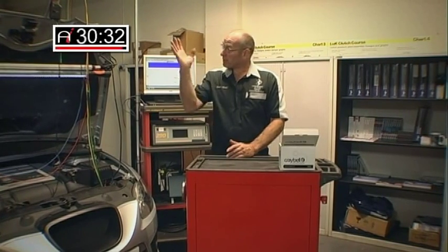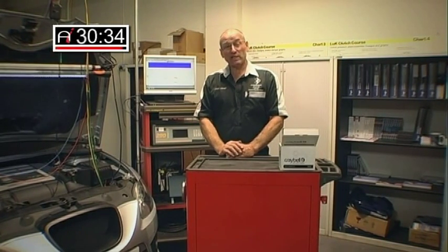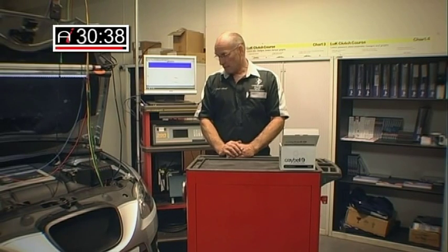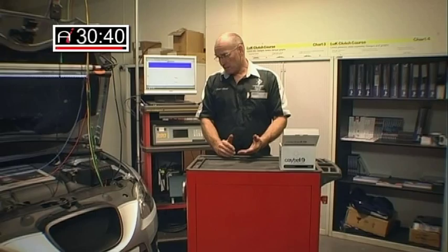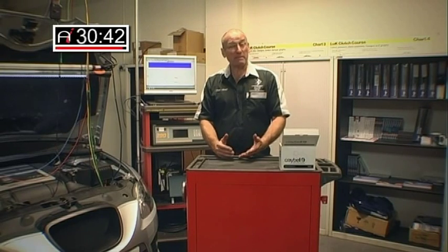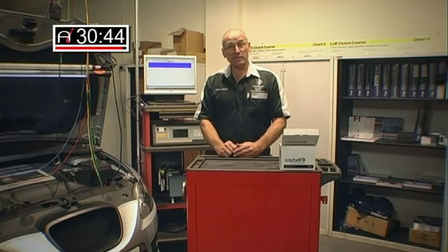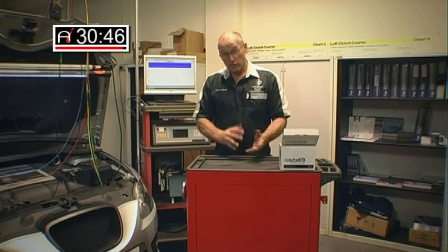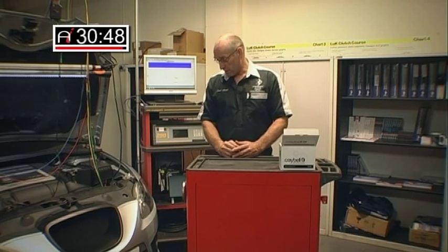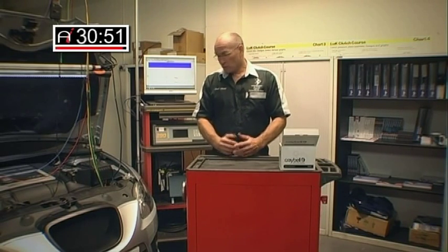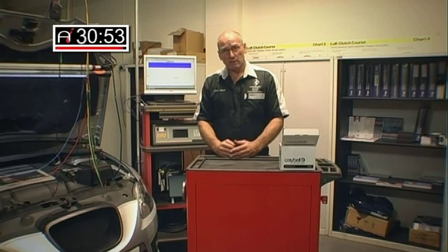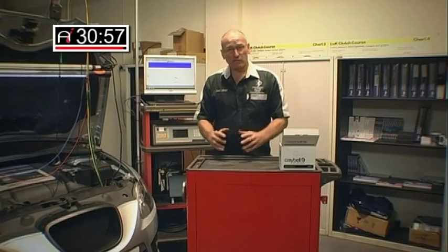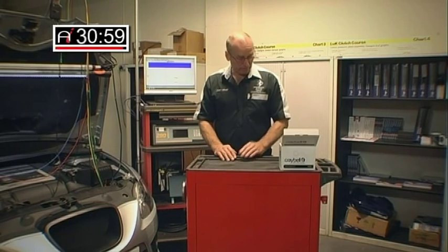The current clamp also serves very usefully for other very high speed current devices, such as anything that's now motor driven with PWM signal, where duty and frequency, and therefore current, change very, very quickly. Turbo control, motorized throttle body, EGR control, variable intake flaps, it just goes on and on. Everything now is motor driven.